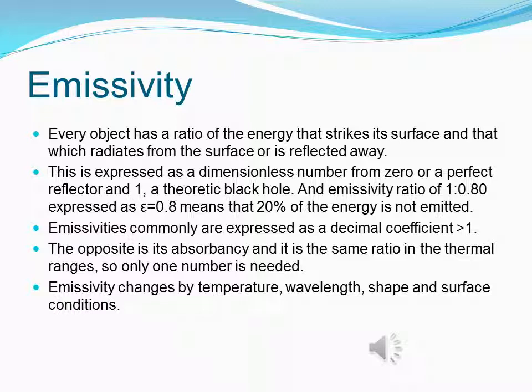So again, in thermograms, sometimes it looks like the insulation itself is the hottest spot when it may be the difference in emissivity. If you have a brand new shiny, let's say aluminum contactor that's put on, but it's put on improperly, it's loose, it's going to start radiating heat.